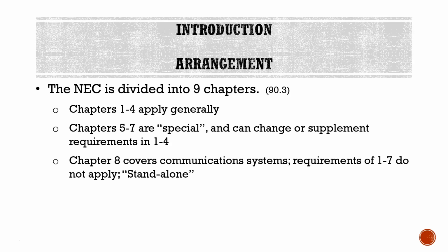Chapter 8 covers communication systems, and for this particular chapter, the requirements of 1 through 7 do not apply. We usually refer to chapter 8 as a standalone chapter. You could, in theory, pull chapter 8 out of the NEC and make it its own code, its own book, because it does not tie into or relate to the rest of the NEC at all.